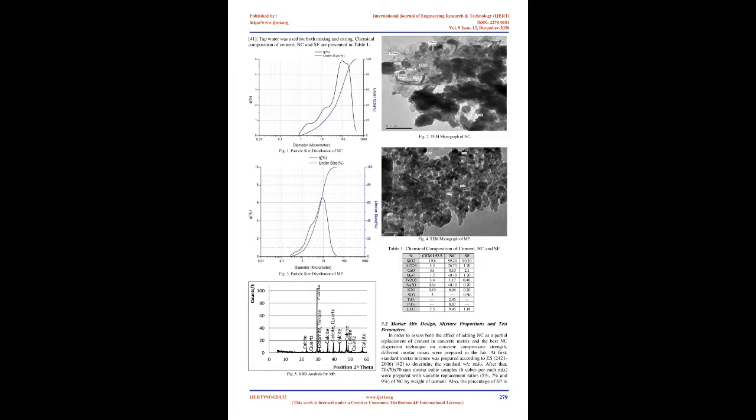Ahmed et al. 30 found that adding agglomerated NC particles using sonication and dispersion techniques in concrete mixture was more effective in enhancing mechanical properties compared to adding NC as received. The optimum ratio of NC as cement substitution was 7.5% by weight for both dispersion techniques. SEM analysis did not detect NC agglomeration in case of sonication and the produced concrete was well compacted, while agglomeration was observed with the other technique.